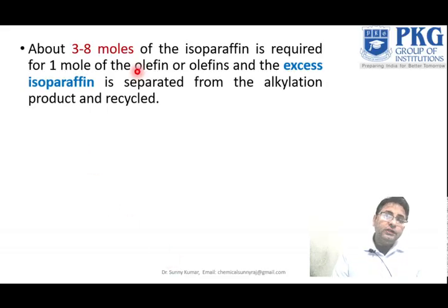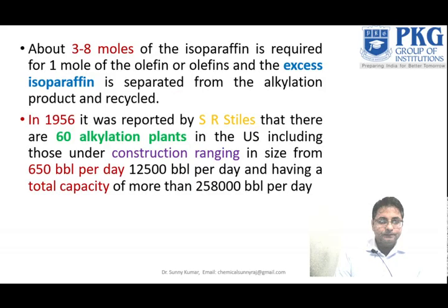So about 3 to 8 moles of the isoparaffin is required for 1 mole of the olefins, and the excess isoparaffin is separated from the alkylation product and recycled.